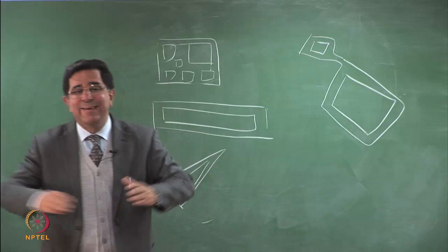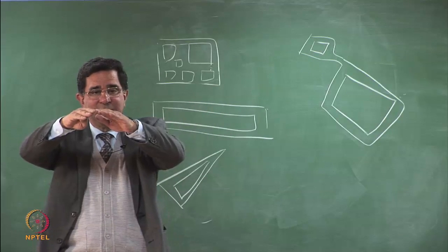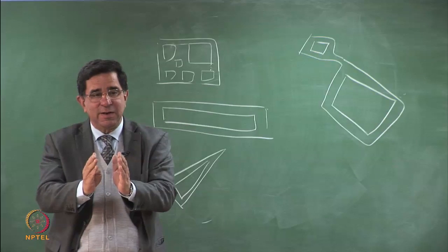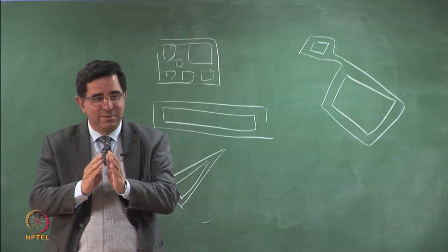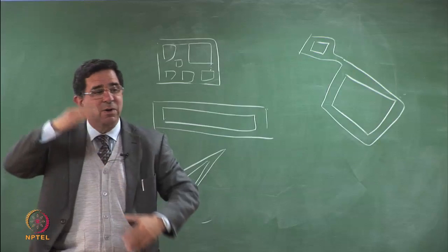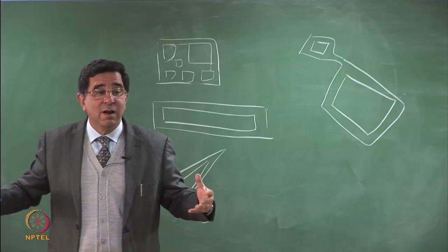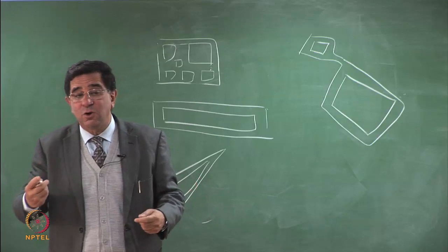Well, if you have a wide base, then your landfill goes up and looks like this. Now you make the base very narrow and make it very long. What happens? The slopes come and hit each other and you can't get to a higher height. So if you want to make high landfills, you need a larger base width of the shorter dimension.